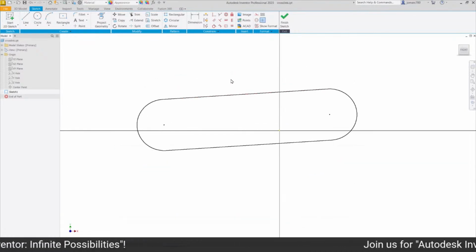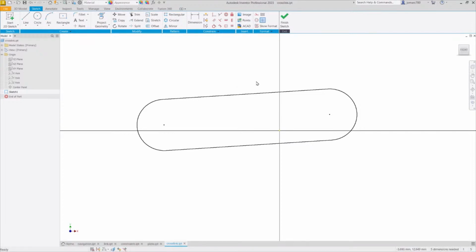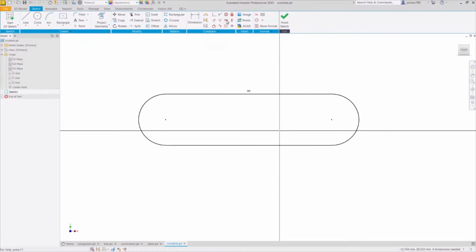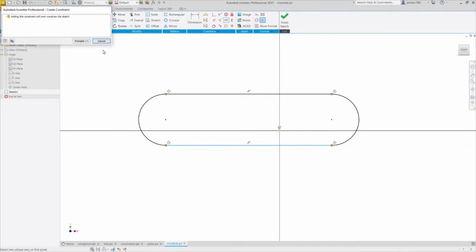I'm going to delete this excess slot. Hitting delete and focus on this sketch. Next, let's apply constraints. Once more, this line needs to be perfectly horizontal. With this selected, I can head up, selecting horizontal, and hit F8 to check. So notice these two lines are already parallel, which means this is already horizontal. And to prove that, as I grab horizontal constraint and apply this to this line, notice I am over constraining.